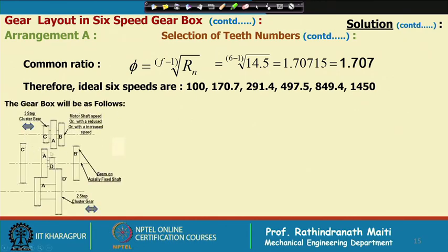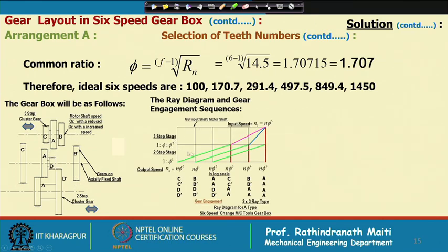Now, again I have shown here the gearbox we are looking for, and this is the ray diagram. So, in answering such a question, you have to draw this ray diagram. A view of this also will be appreciated, not of this form, it might be a more freehand sketch, like this. We can make this gear like this, and the mating gear may be like this, all gears on a shaft.